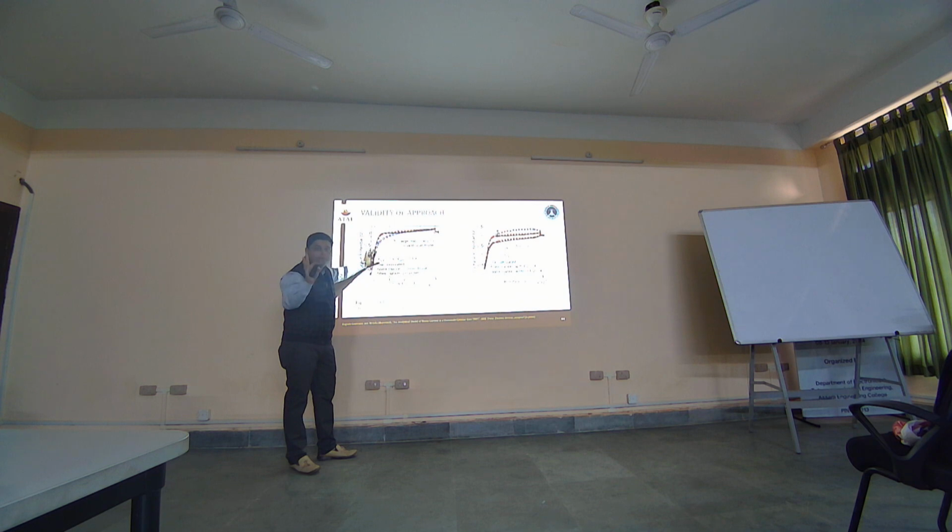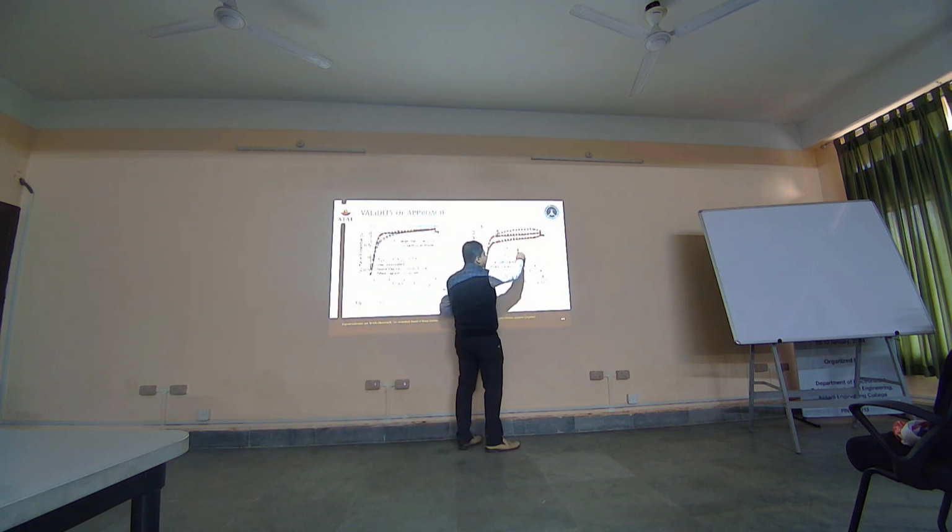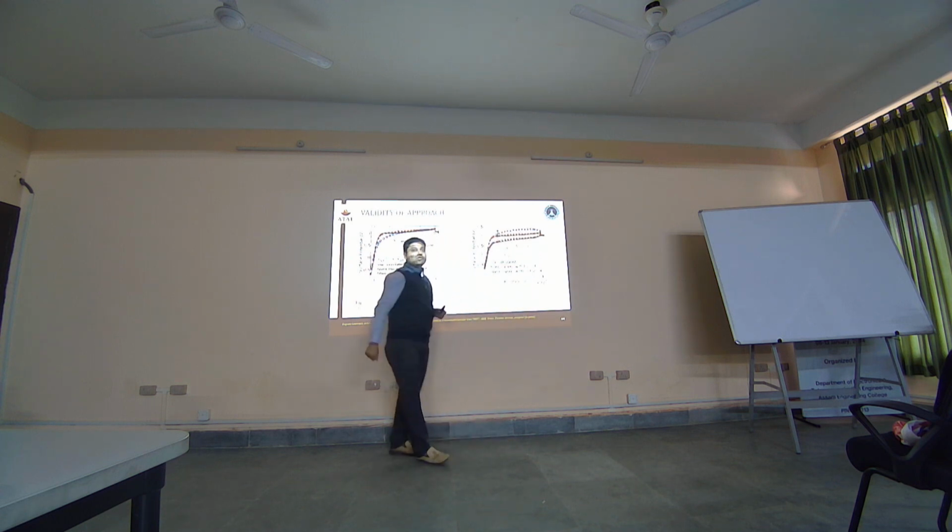Secondly, that was solved. We first started with SiO2, which has a permittivity of 3.9. So that was solved for us in the first instance. But now we have to validate our model for higher dielectric constants. We went for it, and then we also checked for higher voltage. And at higher voltage, it was giving this level of inaccuracy.